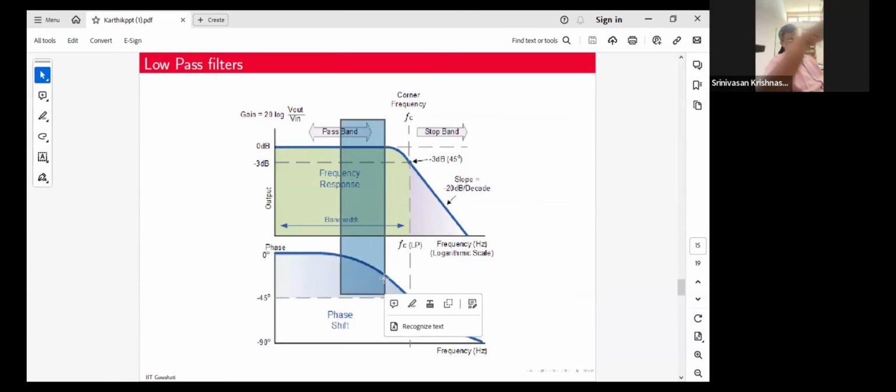So higher frequency signals in this range have greater phase delays, and the lower frequency signals have lesser phase delays, which means that your signal will start getting spread in time. Although there would be no distortion so far as the magnification is concerned, you will begin to have distortion so far as your phase is concerned.